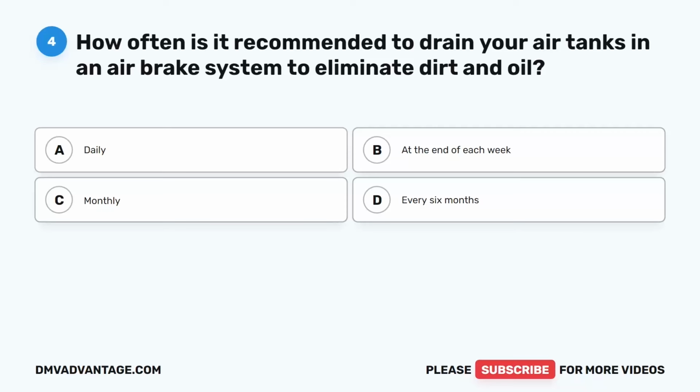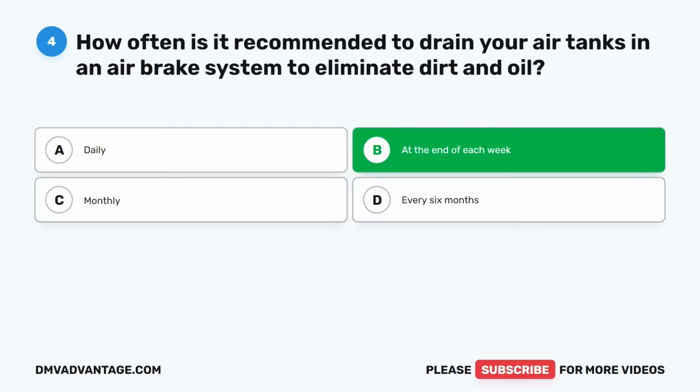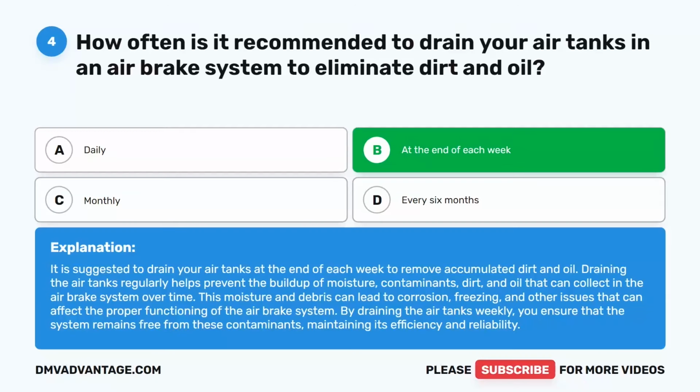The correct answer is B. At the end of each week. It is suggested to drain your air tanks at the end of each week to remove accumulated dirt and oil. Draining the air tanks regularly helps prevent the buildup of moisture, contaminants, dirt, and oil that can collect in the air brake system over time.